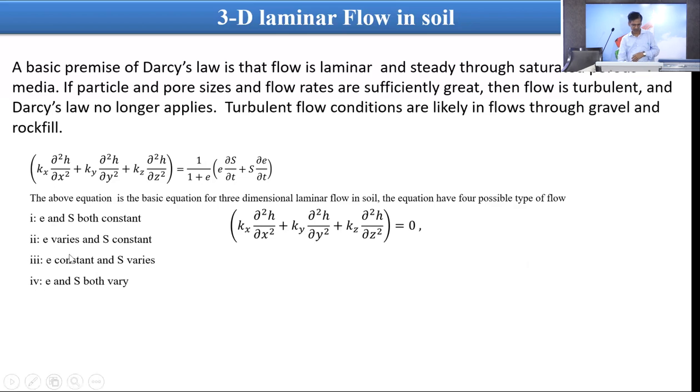there is a case, suppose it is compaction and I have done the consolidation. When we say consolidation, the water is already saturated, I assume. Then I put the load. What is changing? The void ratio is changing. S remains constant, this e is changing, so this term becomes 0, and only this remains. Sorry, the degree of saturation is constant, so this will be 0, and I have only del e by del t, the void ratio changing with time. So that is the consolidation equation.